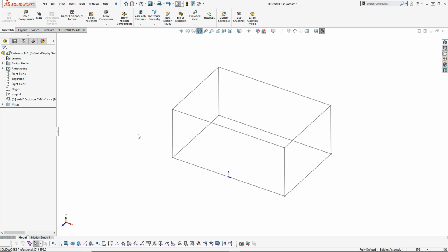Alright, so for the sheet metal you have the choice of, again, if everything was conveniently the same size or not that complicated. As we got into the more complicated bends, I would probably have a part sheet metal 1, part sheet metal 2, going through the entire structure so that I could keep track.